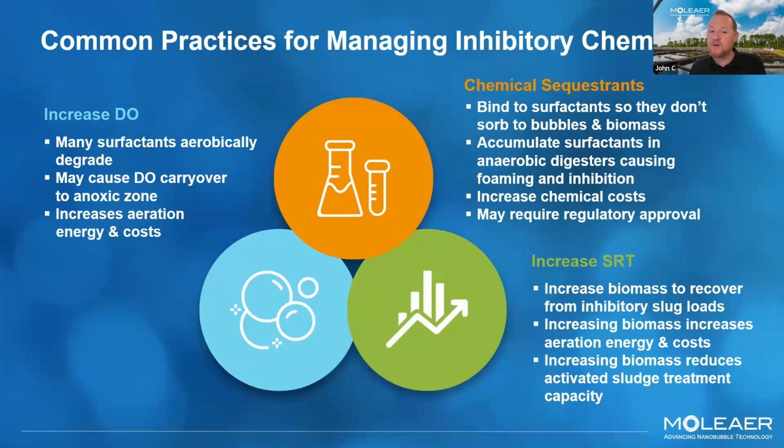And so you're using chemical sequestrants. They bind to surfactants so they don't absorb to bubbles and biomass. Unfortunately, they still end up in the solids that go to anaerobic digestion process, causing foaming and inhibition and poor gas production. These chemical sequestrants are extremely expensive. And if you're discharging to a water body, it may require regulatory approval.